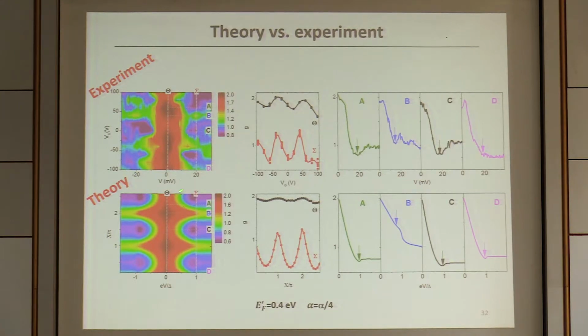So of course, you get this alternating conductivity in which you have enhanced and decreased conductivity as a function of the gate voltage, which here appears as a phase. You have this modulation of the conductance for these two cuts that I selected here. And also you can do cuts in this direction and see that the shape of the conductance curve is fairly well reproduced by the theory.